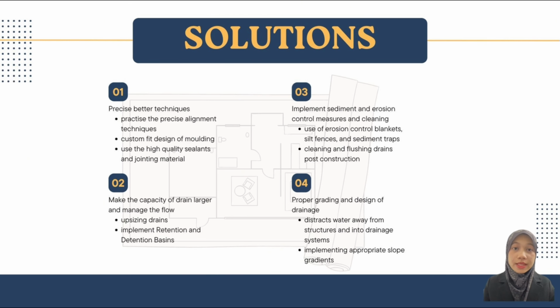First, upsizing drains, to accommodate a large amount of water runoff. Upsizing drains requires enlarging the diameter and capacity of drainage pipes and channels. Then, implement retention and detention basins. Detention basins are used to temporarily hold water and release it at a controlled amount.